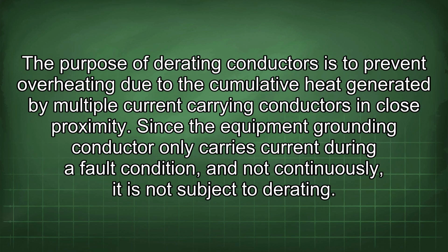conductors. The purpose of derating conductors is to prevent overheating due to the cumulative heat generated by multiple current carrying conductors in close proximity. Since the equipment grounding conductor only carries current during a fault condition and not continuously, it is not subject to derating.